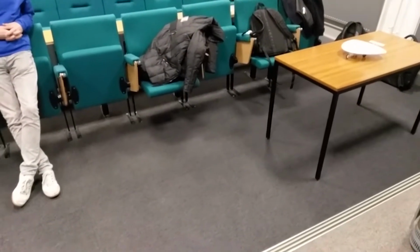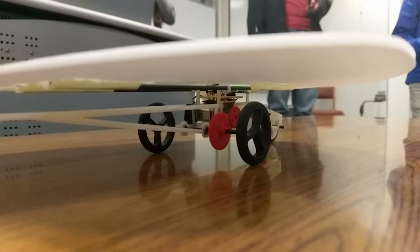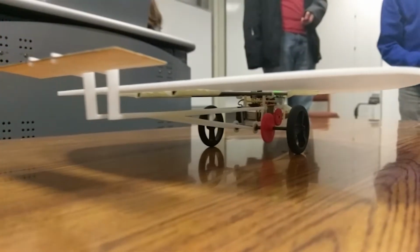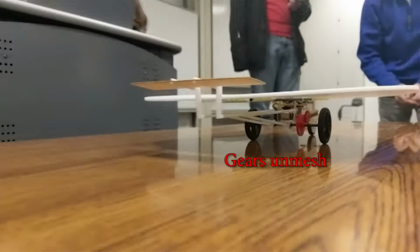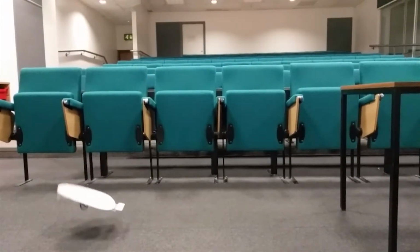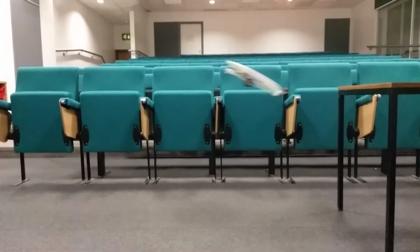During the first test, conducted at a height of 0.7 meters, it can be seen that our model faced several issues. The gears connecting the motor and wheel axle would unmesh before the model reached the end of the ramp, resulting in a severe loss in velocity. One positive takeaway, though, was that our model travelled in a straight line. Secondly, the glider would pitch up significantly due to the presence of a tailplane, leading to a reduced distance as the model stalled. With these results and problems identified, the next phase was to improve on our existing model.